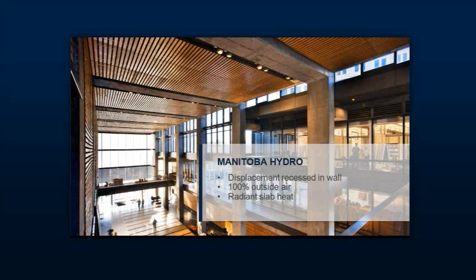Now, this was not a smoking structure, but we have many casinos where displacement's been used because I'm stratifying this room. I'm moving all the heat and the contaminants to upper levels, and if you have somebody smoking, that smoke byproduct is typically warm, and you can watch the tendril of smoke from the end of a cigarette float up to the ceiling level. It never dissipates really.